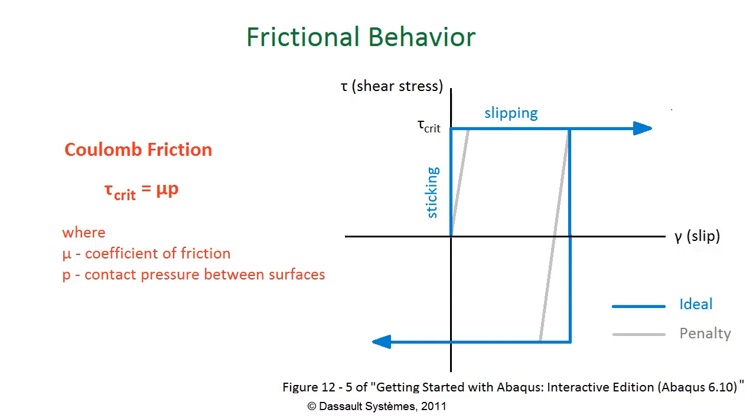If you wish to enforce ideal frictional behavior, go with Lagrange multiplier. With this formulation, there will be no slip between the surfaces until the shear stress has crossed the critical shear stress. The rough formulation specifies an infinite coefficient of friction, meaning that there is no slipping between the surfaces no matter how high the shear stress. And user-defined allows you to specify the shear interaction with user subroutines.